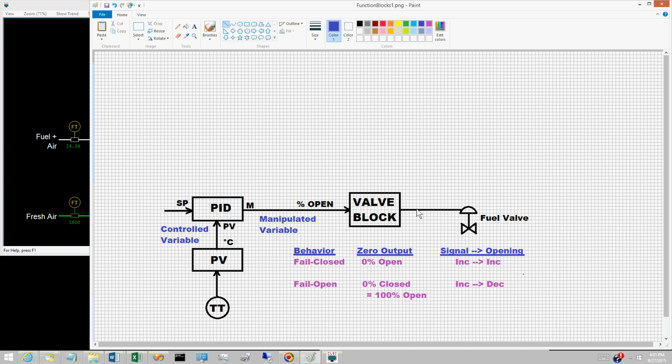On loss of control signal or loss of power, that is, supply air, the pneumatic diaphragm actuator can be configured to fail either fully closed or fully open. For loss of power to an electric actuator, a cost-effective approach to provide such behavior has so far proven elusive.